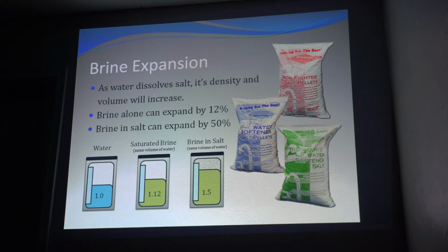Well, what are the options? If you spend that $900 on a grid, or whatever it costs you, get something that's going to support your salt up there. You can use whatever salt product you want, and you're not going to run into those kinds of issues. That's usually the recommendation: clean your brine tank out, pop a grid in there, and you can use whatever you want. And all of a sudden that $900, after a couple of months, is getting you savings.